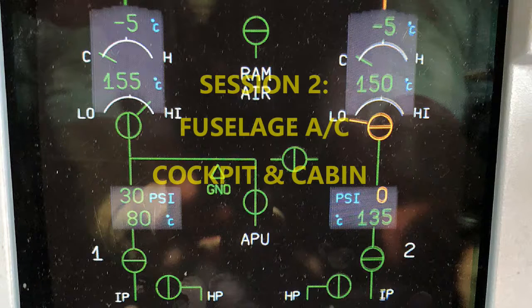I mentioned the valve opening and closing. With the exception of the closing of a valve on the trim air pressure regulating valve, that's something that the secondary computer can actually do. So I'm just giving you, you don't have to memorize all this. I'm just sharing with you that there are some things that the primary computer does that the secondary computer is not going to do. But for the most part, the secondary computer is taking over most of the functions in the event that there's a failure of the primary.